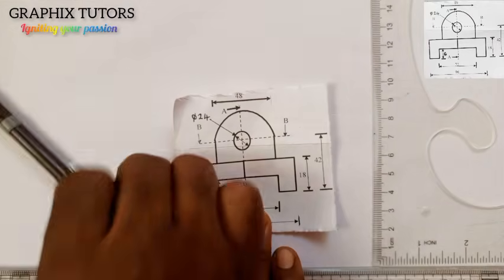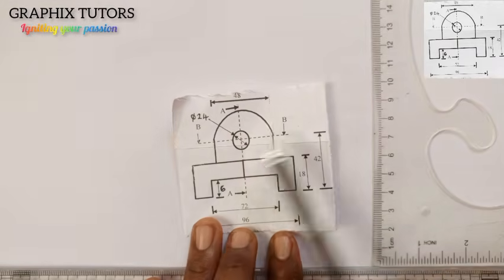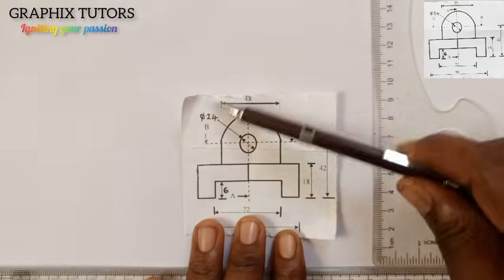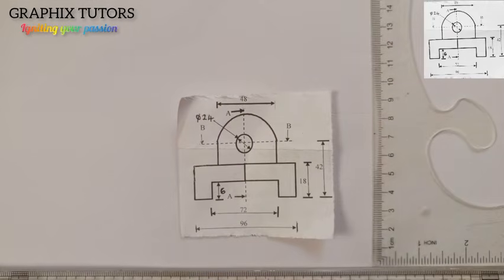So we should show the side view section AA looking at this side, and we should show the top sectional view looking from the top. Now you might be wondering, where can I start in doing this kind of exercise or problem? The first thing you have to do is represent them in an orthographic projection. If you like, you use third angle projection, and if you like, you use first angle projection. Now I'll take you down memory lane where we can draw this.